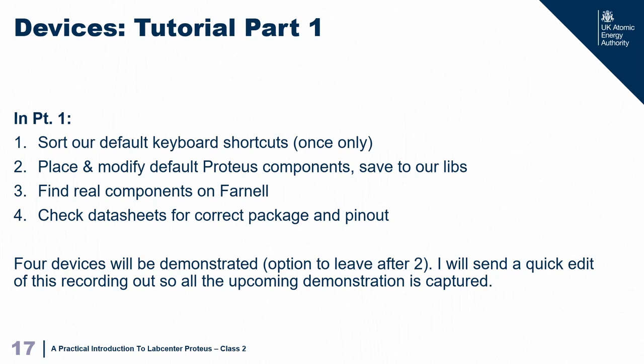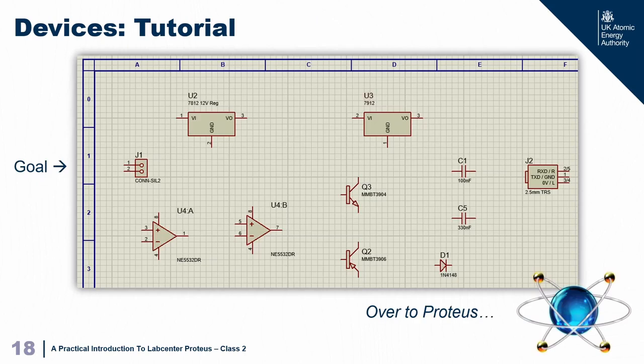We're going to find a component, open the data sheet, and check that our footprint matches the device that we're going to buy. Make sure your pins are in the right place. Because if you create your circuit, get it made, and you've messed the pins up on your footprint, everything's connected to the wrong point, or maybe the device doesn't fit. So this is all quite important to do.